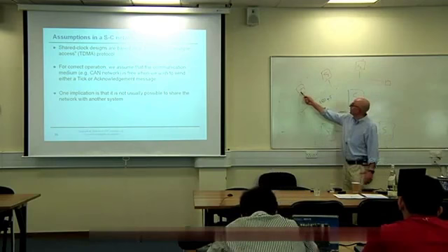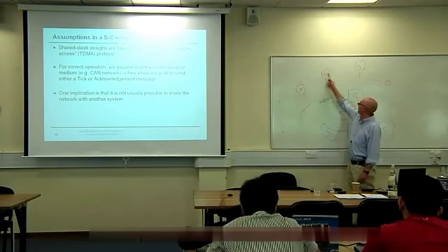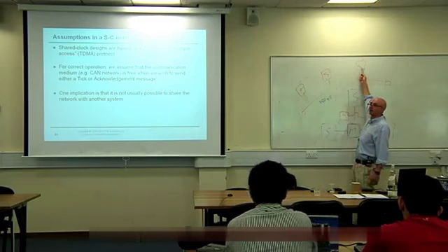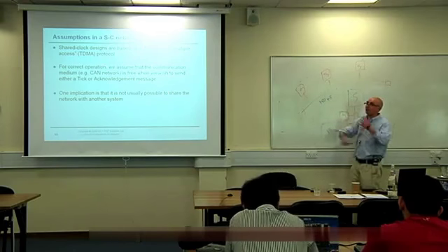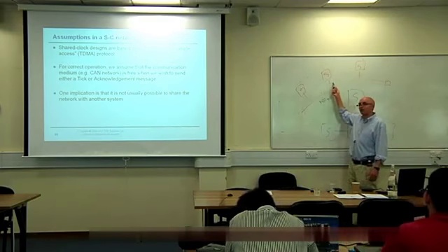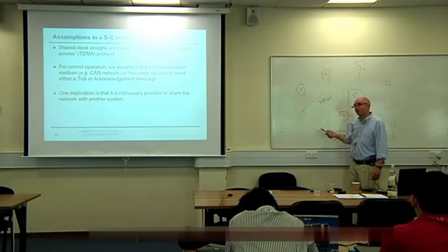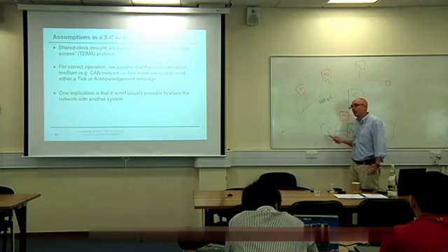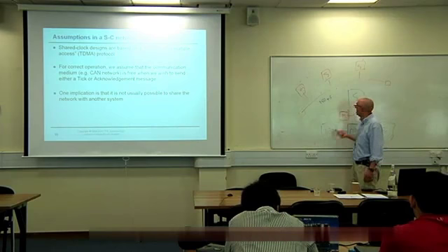This might be getting the data. This might be doing your H infinity or PID control algorithm. This might be your actuator node. And that's quite typically a structure of it. So we need the data over here pretty promptly so we can do the calculation, and we need to get the data out again at the other end pretty promptly so we can do the actuation operation.